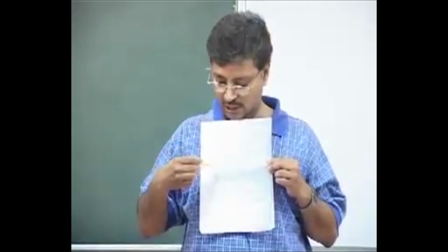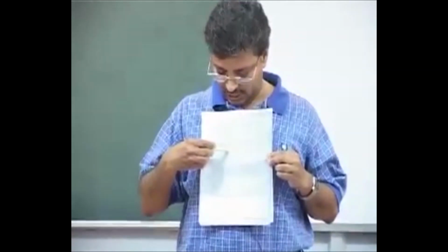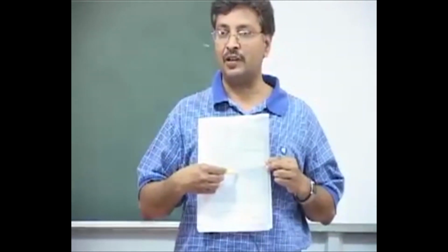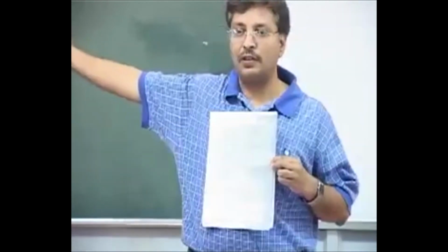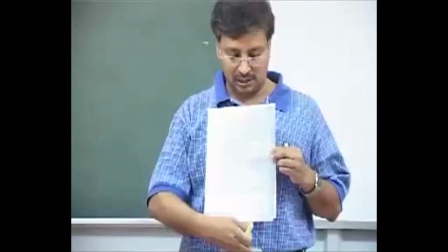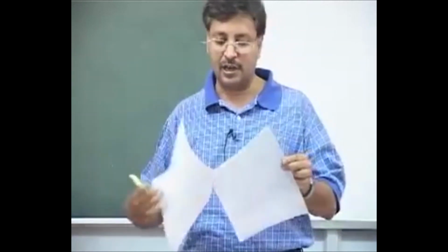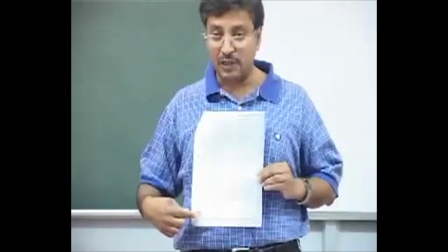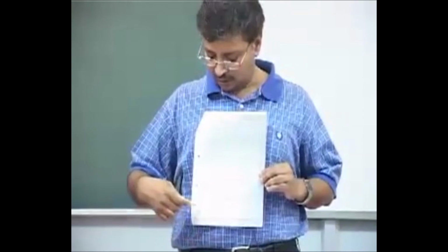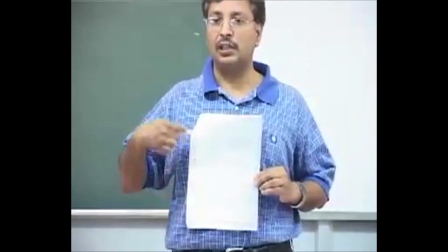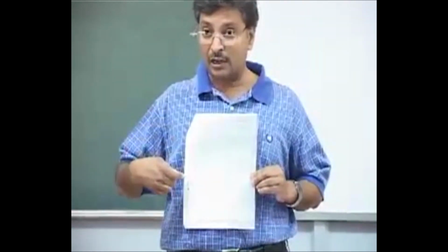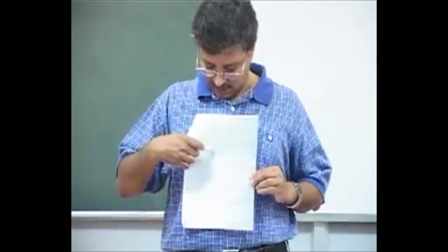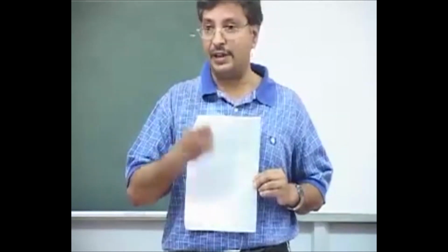These are the values of sigma y for stability A, B, C, D, E and F. And then the same thing for sigma z, where you see more curved graphs, with the same downwind distance on the log scale and the value of sigma z on the y axis, again log scale, for A, B, C, D, E and F.